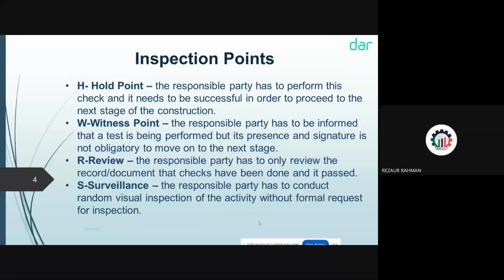Sorry, one question: why does the consultant not inspect before the third party? This is a requirement. The consultant should. The testing, for example compressive strength, or a hydro test. Hydro test is actually site testing. This is different. This is not the third party, right? For the hydro test, the third party is also doing the witness.